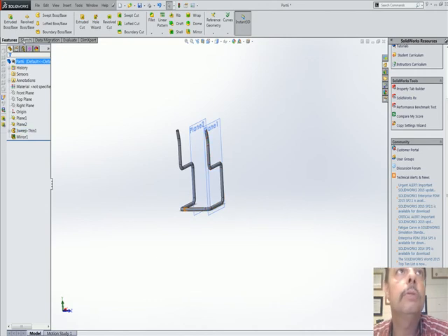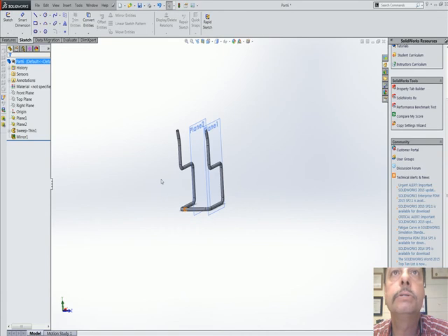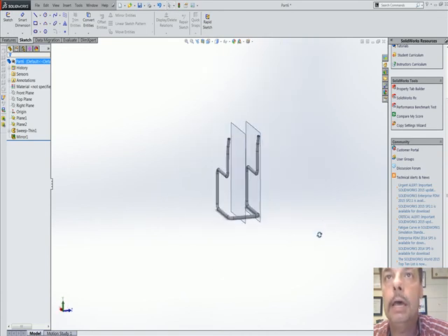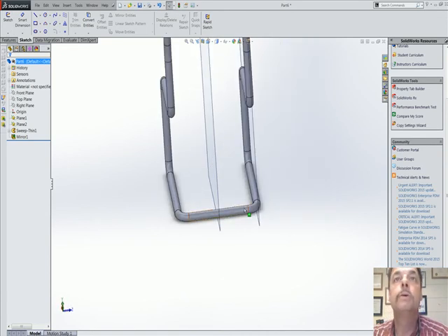The key is that since there is a direction of it, a Z and a Y this way, that's why you got to go to 3D Sketch. 3D Sketch allows you to sketch outside your normal front X and Y, right and top X and Y. Okay. Any questions? Let me know.